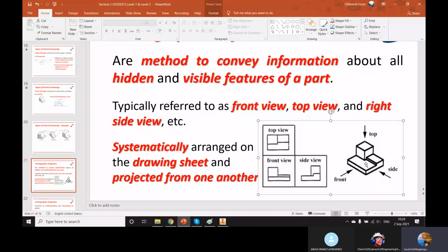I do. All right. So that's what's shown here now. This first face is this, and then this is this. Then if you're looking from the front, you'll see 3 faces also. You see this face here, this other face, and this face. You're not going to see this face again if you're looking from this front view. You will not see these other faces. You'll see just these 3, and that's also what's shown here. And if you're looking from the side, you'll see just 2 faces. You'll see this face here, and you'll see this face.